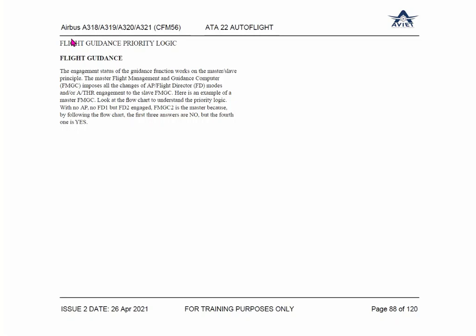But in autopilot, in this FMGC condition, that is not the logic. If we select autopilot 1, then FMGC 1 will be on the priority side, I mean, it will become master. Even the command will come from FMGC 1.